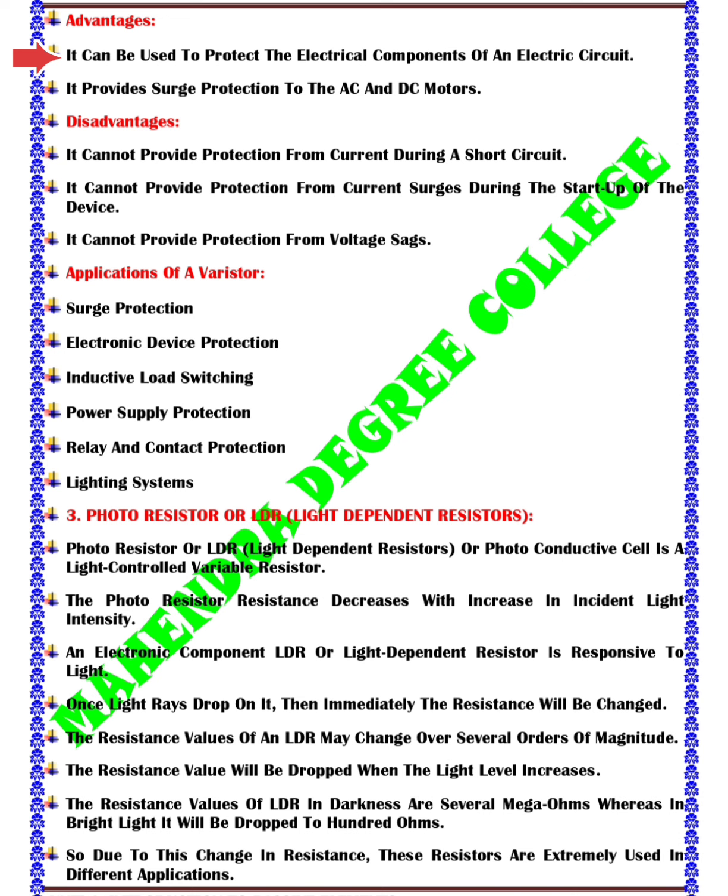Varistors, also known as metal oxide varistors (MOVs), are designed to absorb and dissipate energy from these voltage spikes, preventing damage to sensitive components. Varistors are used as control or compensation elements in circuits either to provide optimal operating conditions or to protect against excessive transient voltages. When used as protection devices, they shunt the current created by the excessive voltage away from sensitive components when triggered.